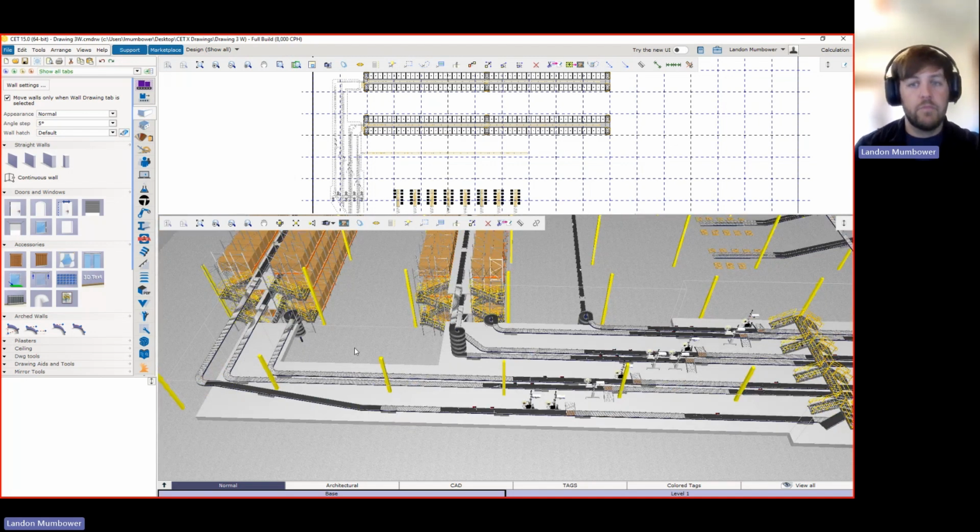So, hey, customer, we've put a spiral here because we need to make sure that we have enough room to gap and scan prior to the print and apply. Over here, we saved you a little bit of money, and we've used a decline conveyor because they are cheaper. However, if you would like more accumulation coming out of that, or you just want everything to look uniform, or maybe there's going to be other processes you need to put on the conveyor here, we can swap this to a spiral. So showing options, but also giving reasons as to what you can do and what you couldn't do.